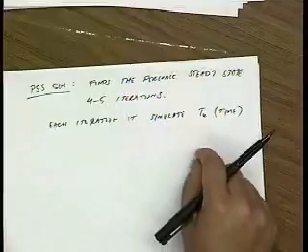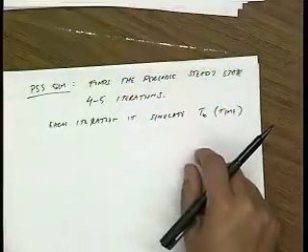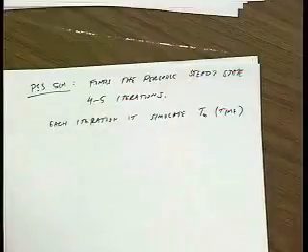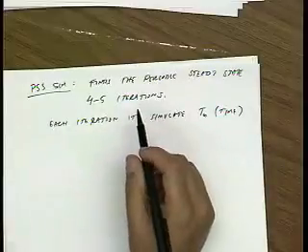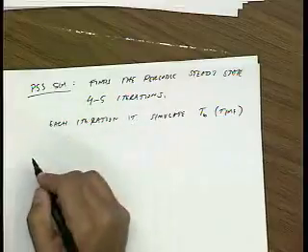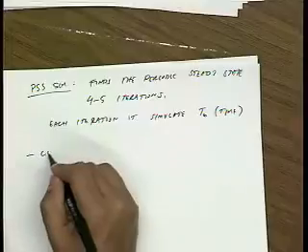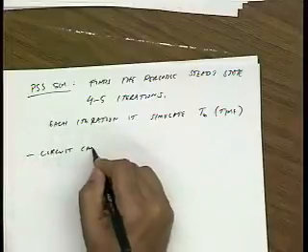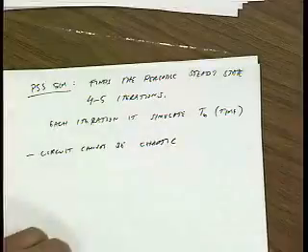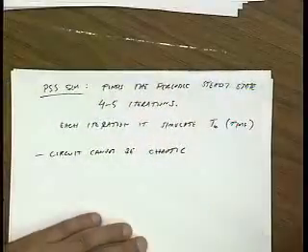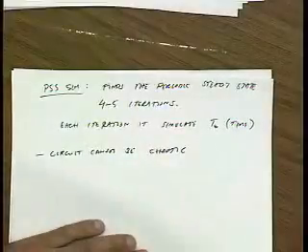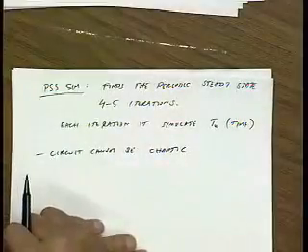The reason it can do this is, let's say PAC. Actually, before I get to PAC, let me just say a couple things here. So there's a couple of conditions for PSS to converge. So the circuit cannot be chaotic. Okay? That means that if I put in a periodic input, the output has to be periodic. It can't just wander off in chaos. Okay?